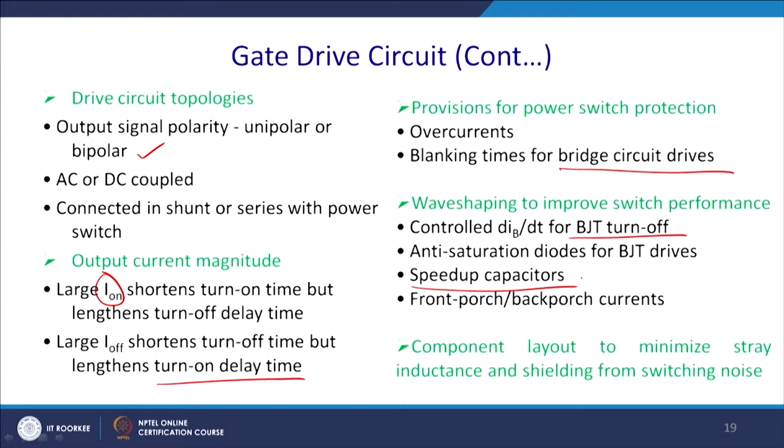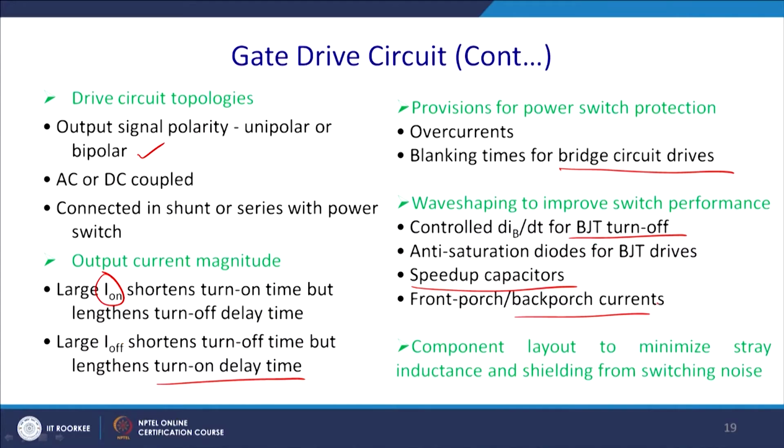Speed-up capacitors make the turn-on faster. A capacitor is something like electrical mass, or electrical inertia, so we have to take control over it. Front porch or back porch current is also something we have to take care of. Component layout to minimize stray inductance and shield the switching noise is very important while designing.